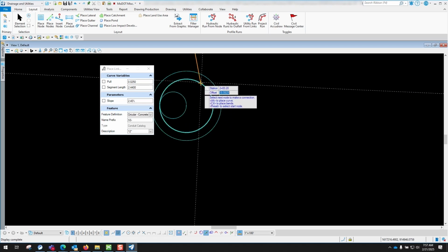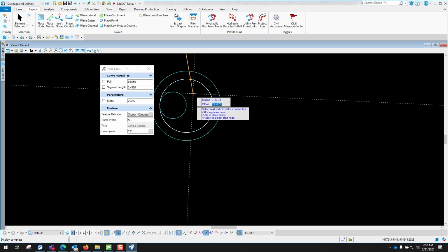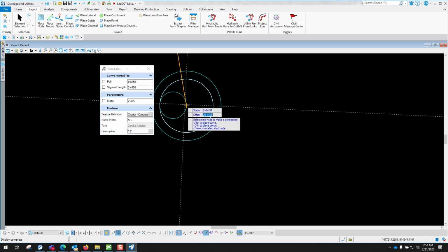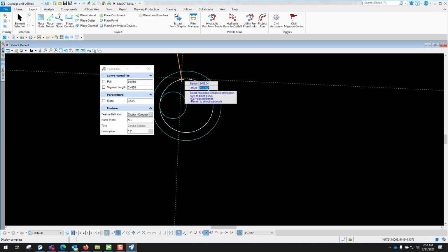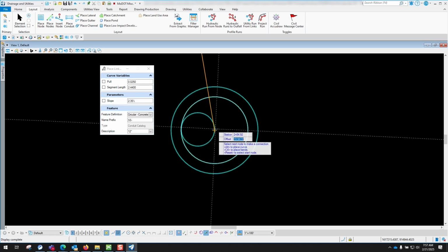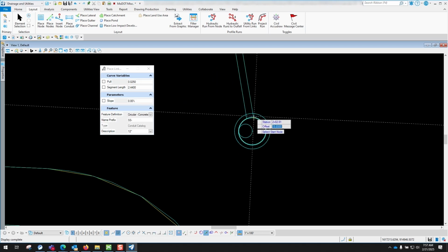Now you can either come over to the side here of this inner wall, or what I would do is come basically to the center of it, which will be right here, and it will actually truncate that back to this inner wall right here. And just to show you that, let me get to the center of it. I'll left click to accept it, and you'll see that it will automatically truncate back to that inner wall.